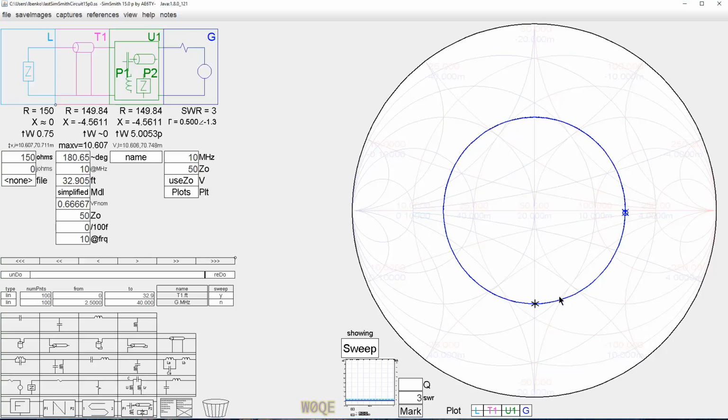it's only using those impedances. What about impedances in here? Wouldn't we like to face our circuit with all those impedances also? And over time, I got myself convinced that an impedance out here on the outside edge of my maximum desired range of impedances would be the worst case for my components here. Not any one particular impedance on this point, on this circle, would be the worst for all the components, but a point on this circle would be the worst for some component, and vice versa, a different point for different component, etc. However, we can do a lot better than that with SimSmith.